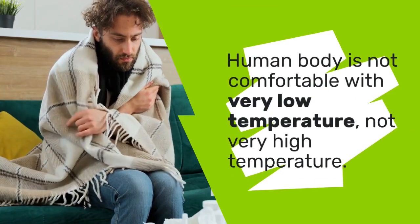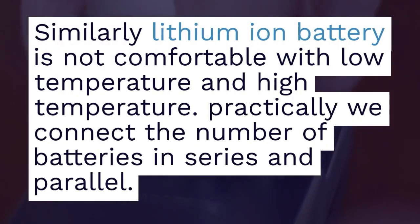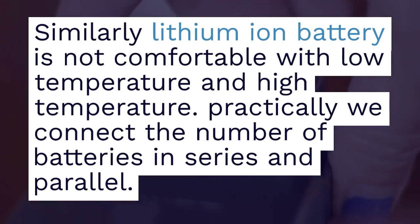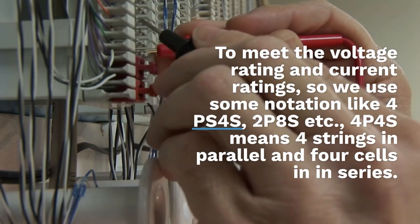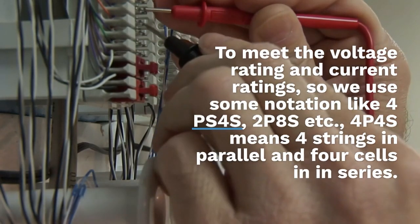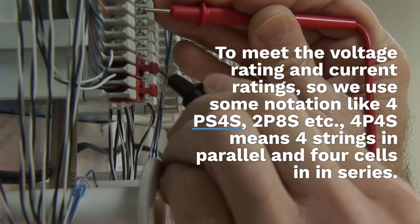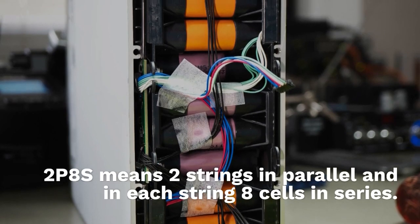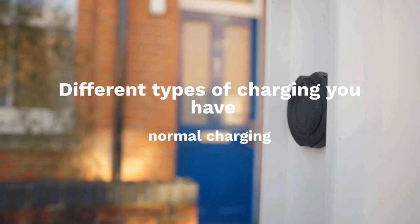The human body is not comfortable with very low temperature or very high temperature. Similarly, a lithium ion battery is not comfortable with low temperature and very high temperature. Practically, we connect a number of batteries in series and parallel to meet the voltage rating and current rating. So we use notation like 4P4S, 2P8S, etc. 4P4S means 4 strings in parallel and 4 cells in series. 2P8S means 2 strings in parallel and in each string 8 cells in series. So that is the meaning.